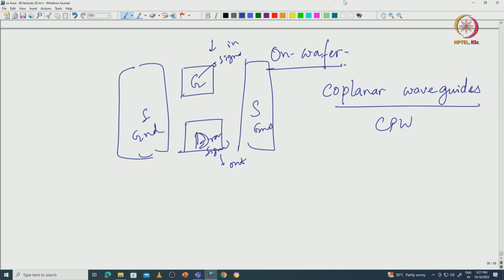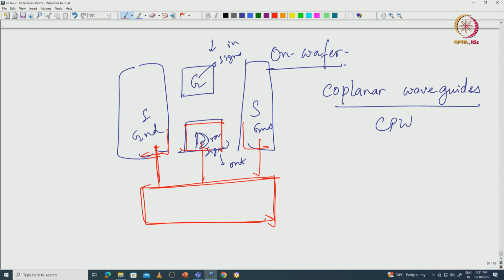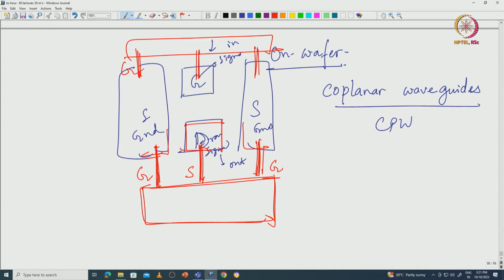So, your CPW pad refers to the fact that you need to design something like that, so that the probe tips come up like that. This is a probe, a manipulator, and the probe tips will come up something like that. So, this is ground, this is signal, this is ground. Similarly, the probe tips will come like that. This is on wafer measurement, okay. This is again ground, signal, ground. We call them GSG probe tips, ground, signal, ground.